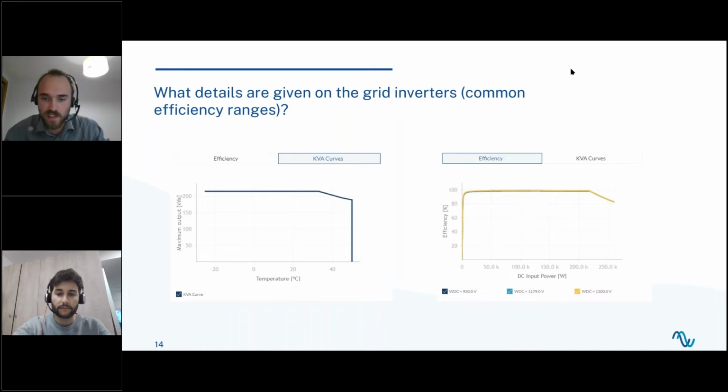So basically these values we will take for each individual inverter. They are uploaded and they're in the OND file. So these are the values we take, and then we get that energy yield based on these curves. And this is the information we have, amongst others.